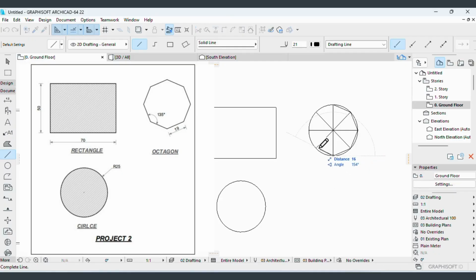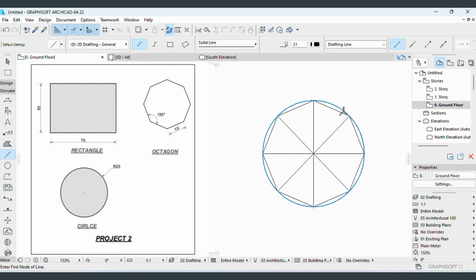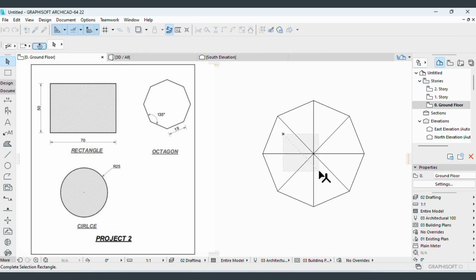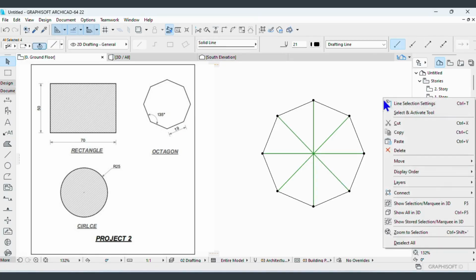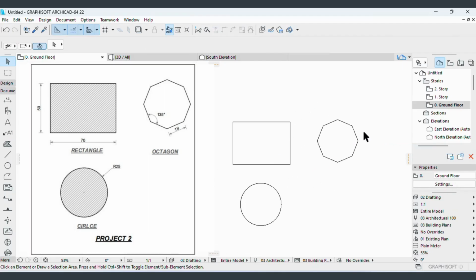Next one. And then the next thing you have to do is to remove the extras, the arcs. So let me zoom in and then click Control and X and then direct your cursor there. Click there, click there, click, and then click. Then we can remove the lines, these lines at once. So let me pick the arrow tool and select all these at once. Then right click outside here, then delete. Then I zoom outside a little.